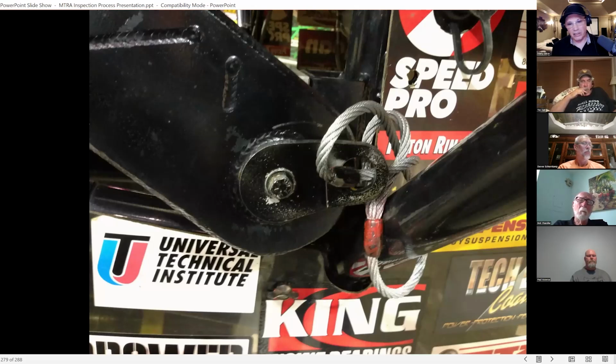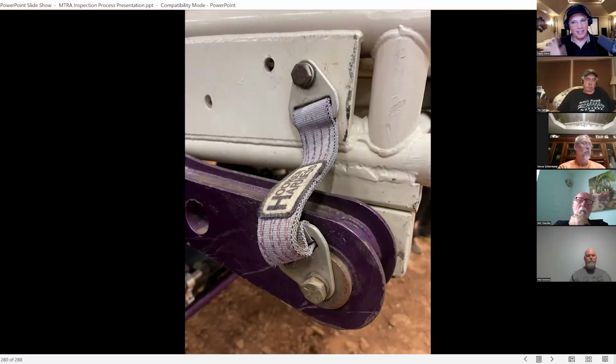Restraints on sway bar links, the sway bar arms, that is one of those things like, how is that a safety thing? Well, it is when the arms get into the tires. We've seen instances where sway bars break. Anybody who's been around the trucks knows sway bars break. We've seen instances where they come out. Depending on where the break happens, the arms can get loose and get into the tires, and the tires can sling them. Honestly, you're protecting the owner from himself. Having that keeps you from doing more damage.